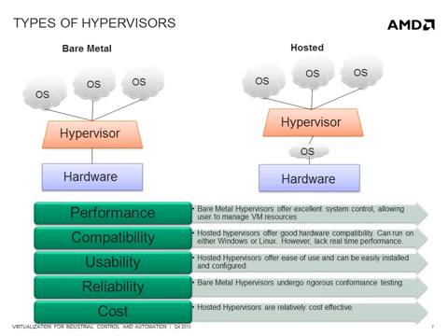The two commonly supported hypervisors in embedded system designs today are native or bare metal hypervisors and hosted hypervisors. Type 1, referred to as native or bare metal, runs directly on the host hardware to control hardware and manage guest operating systems. Type 2, or hosted hypervisor, runs on the host OS. In this case, the guest operating system runs at the third level above the hardware.